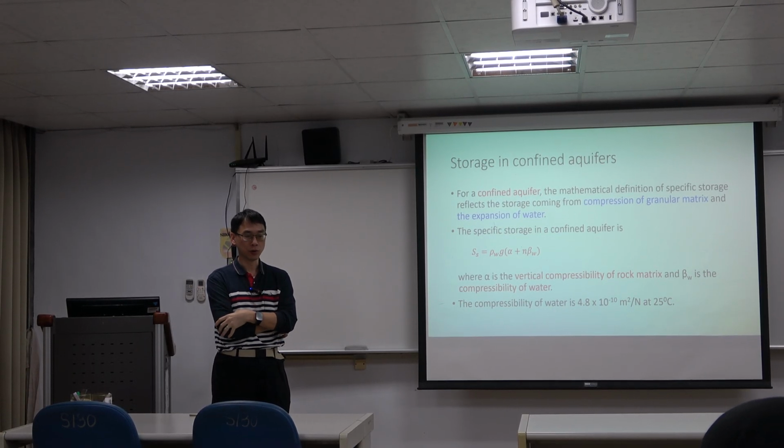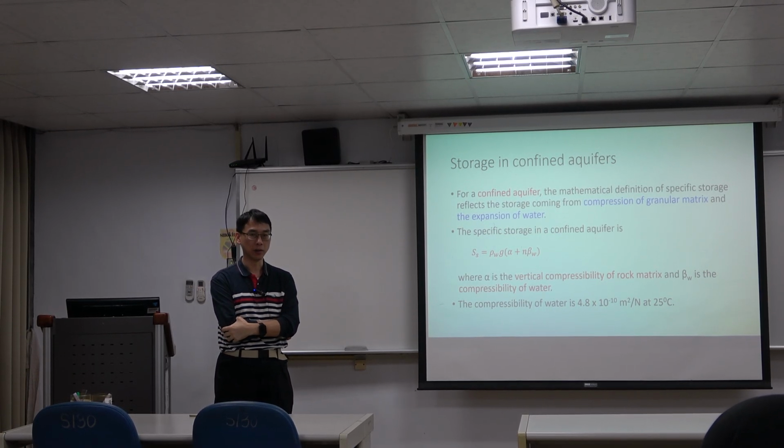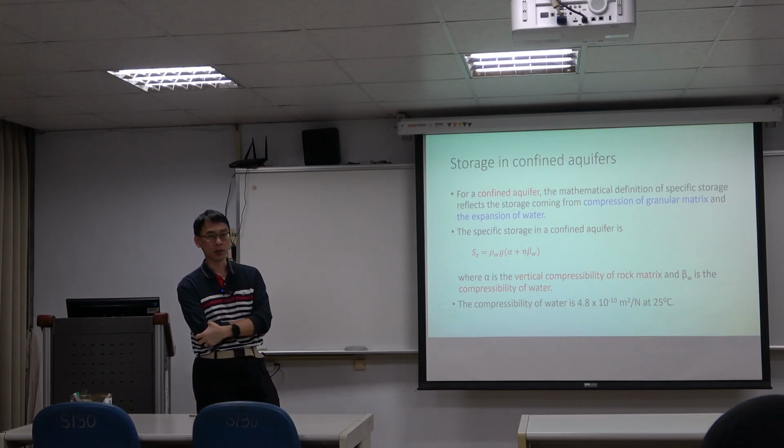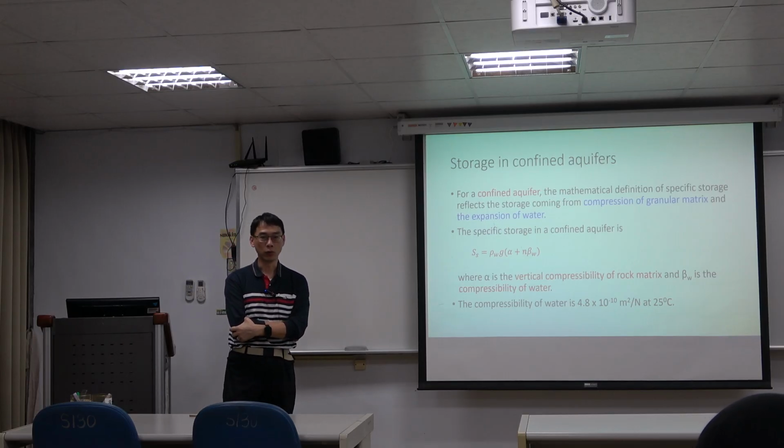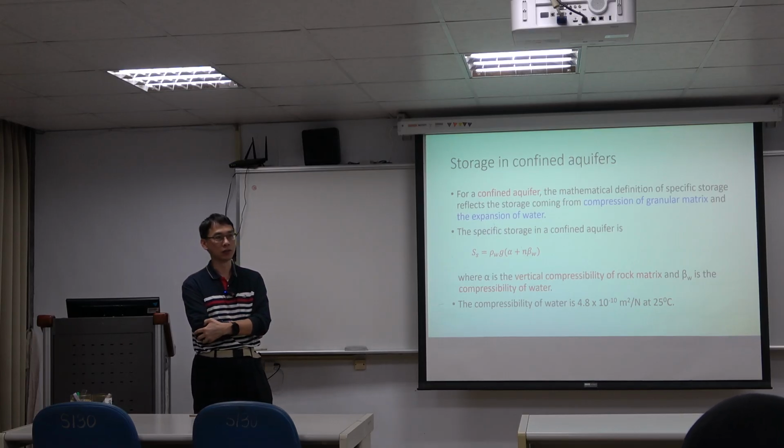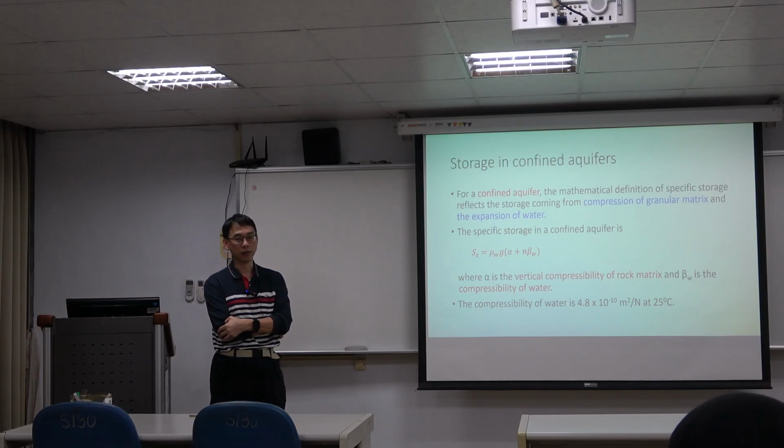Yeah, sure. If you take the core sample back to the lab, commonly the quantity will be affected. One reason is that they release the stress. They will have different behaviors because they expand or become looser materials, so the K value will be different. But another is the scale effect.